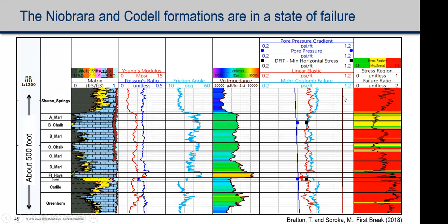And Mohr-Coulomb says that the vertical load, which is this guy, and the horizontal, you're going to be at Mohr-Coulomb failure long before, and so the linear elastic model is not a correct reflection of the stress. It says you can stress the rock all the way from here's your vertical load, here's your horizontal load, and it's too different. You can't support that.